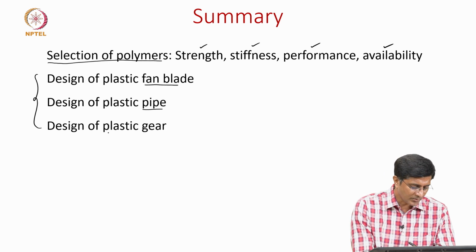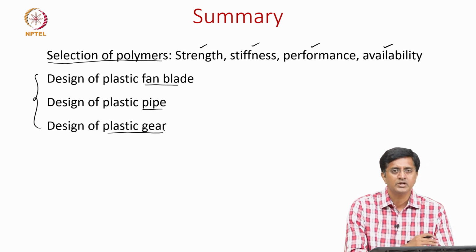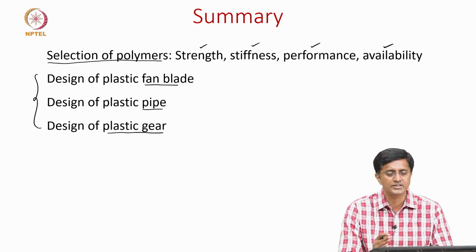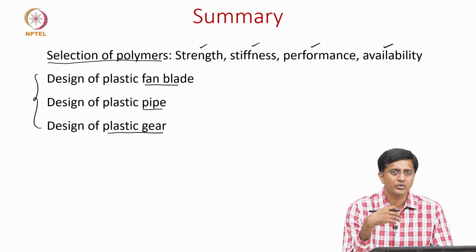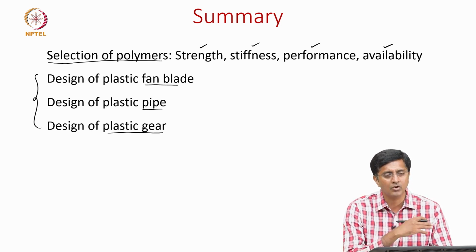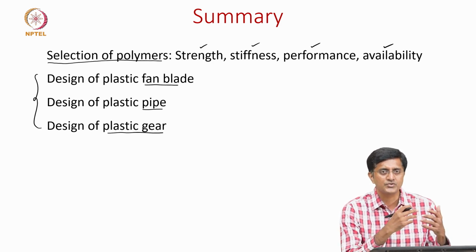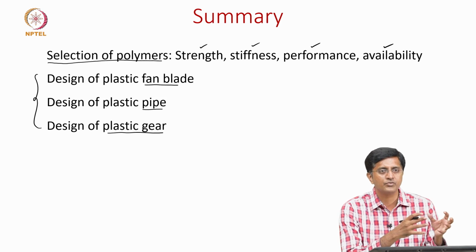Lastly, when we touched upon plastic gears, we have seen there are several advantages of using these gears, but there are a few disadvantages one needs to keep in mind. And finally, when we are looking at the design, especially how do we take care of temperature and humidity effects, we said there are several aspects to look into. But lastly we also mentioned that there are some options where there can be no lubrication if they are at low speeds because of the low coefficient of friction.